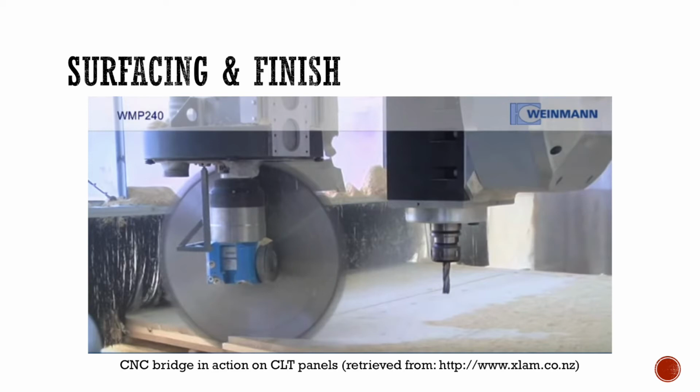The CLT panels are then sent to a machining station for fine cutting and jointing. This work is most often performed by a multi-axis CNC machine. It performs pre-programmed sequences using the shop drawings to accurately cut the openings for windows, doors, splices, joints, connection points, mechanical and electrical rough-ins, or any other required openings.